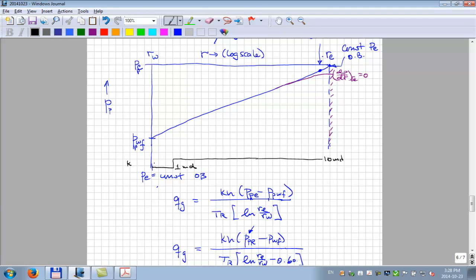And because of this lower permeability, this is our damage. What's going to happen to the pressure drop? Well, it's going to be the same here, but then when it comes down in this region, it's going to have a slope 10 times steeper. I'm not going to go from 10 to 1, because that's a lot steeper. Maybe I'll go from 10 to 2 or something.